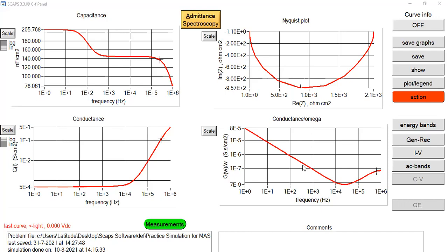about the EIS analysis for perovskite solar devices in SCAPS-1D, and I have explained the effect of a set range of input frequency on capacitance and conductance, and the effect of the input applied AC signal on the impedance of my perovskite device. When we simulate the Nyquist plot, we will always have the same kind